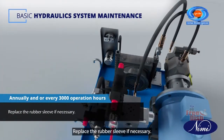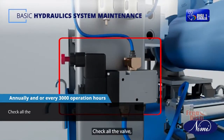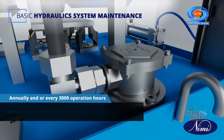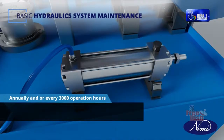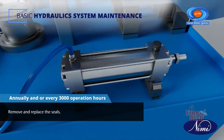Replace the rubber sleeve if necessary. Check all the valves, pumps and actuators for oil leaks. Remove and replace the seals if necessary.